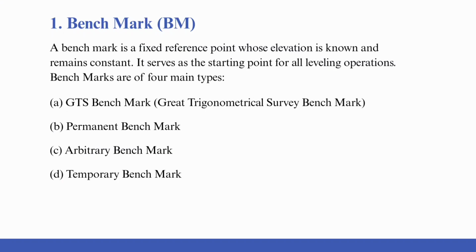Now the very first terminology is BM, that is benchmark. A benchmark is a fixed reference point whose elevation is already known and remains constant. It serves as a starting point for all leveling operations, and there are different types of benchmarks like GTS benchmark, we can say it as a Great Trigonometrical Survey benchmark, then permanent benchmark, arbitrary benchmark, and temporary benchmarks. We'll see one by one all the types of benchmark in detail.